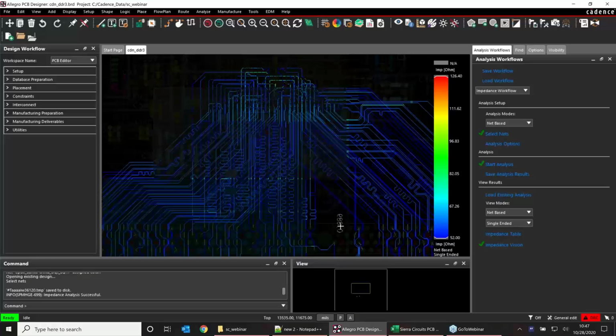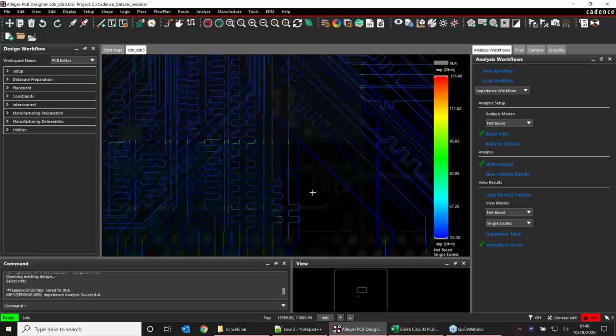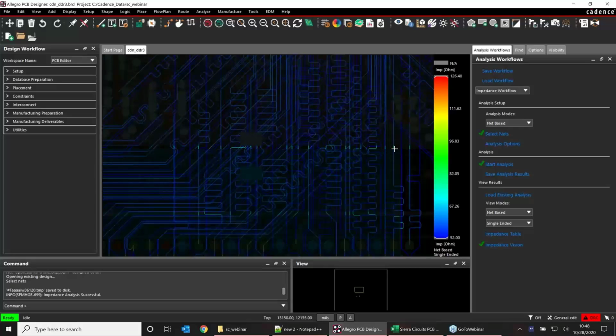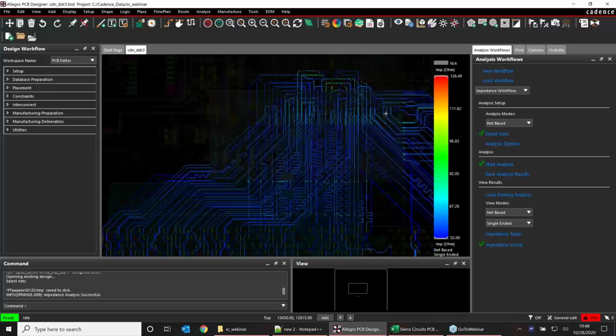And you can see some interesting things as you're going through here. You can almost see shadows of something that's happened here. There's a line going across here that appears to have a different impedance. There's another one here as well. And up here we've necked down to get into our components. You see the impedance change there as well. And here's some more ribbons of discontinuity. What's actually happening there is we're going over a reference plane, and it's causing that problem.